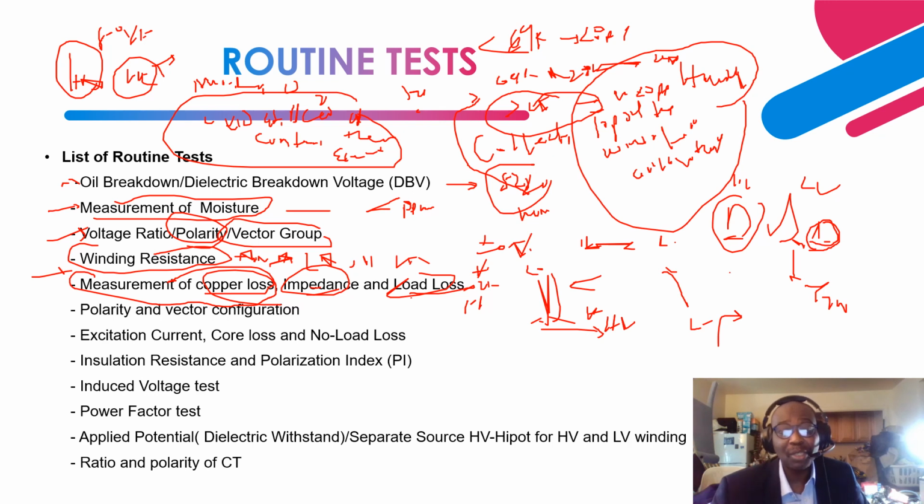The wattage is equal to the current and the voltage, right, times √3. So that is the amount of wattage that is fed into the transformer during the temperature rise test to determine that your transformer temperature rise meets design criteria. Next is polarity, right? And polarity, I think we did discuss it over here. Next is excitation current, right?